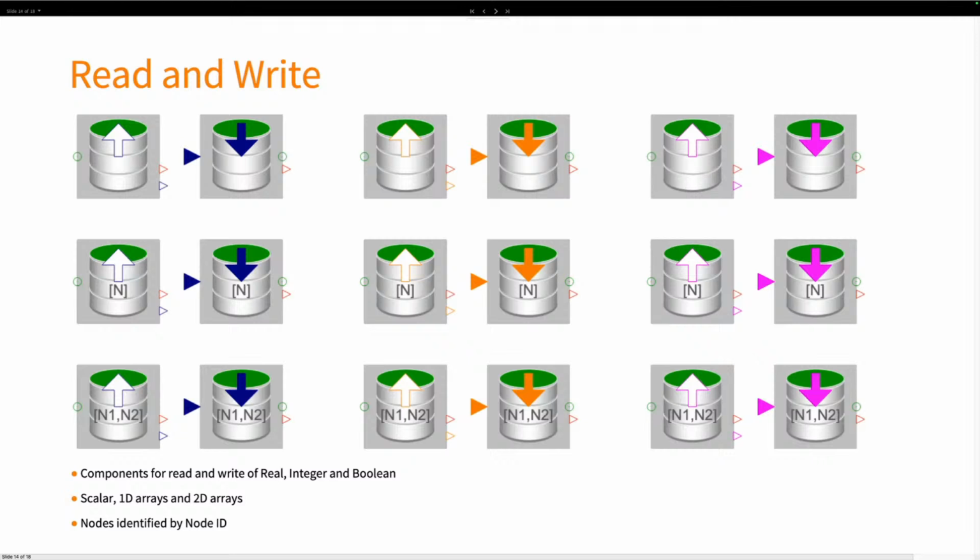One thing is that OPC UA has a richer list of types than Modelica, which is used in System Modeler. So for example, it has unsigned and signed integers in all combinations of the usual width variants, whereas in Modelica we only have one basic integer. So when writing data, we must also specify the specific OPC UA data type that should be used for the write request.